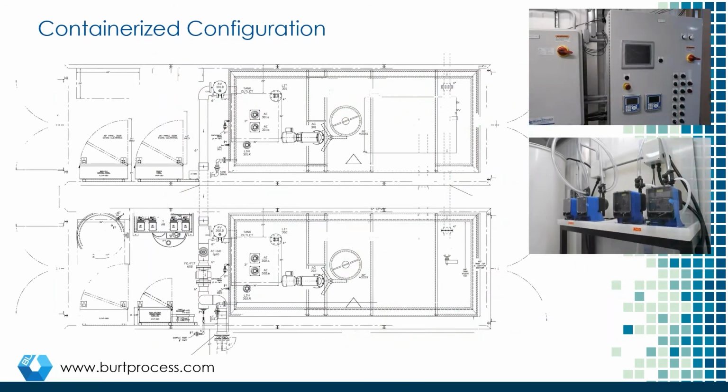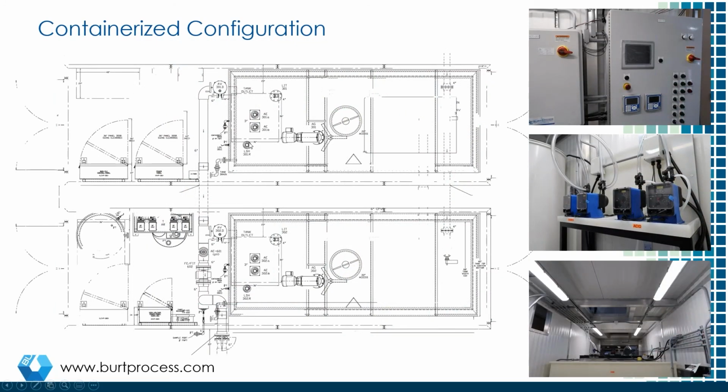And looking at the inside of the containers here, you can see the tanks obviously occupy basically about half of these units. You have top access here located right here above the agitation. Back swing doors so the tank itself can be removed if it ever has to be for maintenance. And really the front section of these then becomes the primary work and operational area. All your instrumentation is located on this side of the tank for access. Your common effluent drain system is also located here. Here you have your fire suppression system, control panels with proper access for lockout, tagout, junction boxes as well.